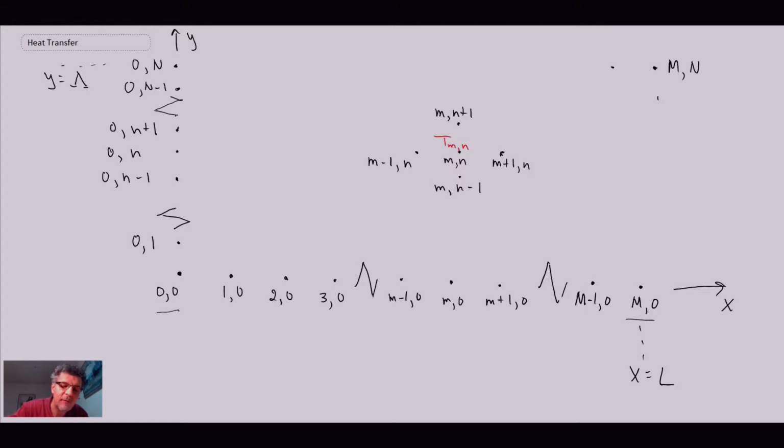And just like we said before, along the perimeter we apply our boundary conditions, which we will be getting to in the next segment. So the boundary conditions would be what is in these nodal locations around the perimeter. But we set up a grid on the inside, and that is what we then work towards solving when we apply the finite difference method to the mathematical physics equation.